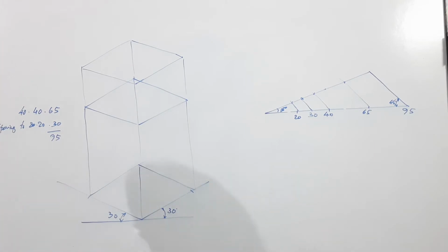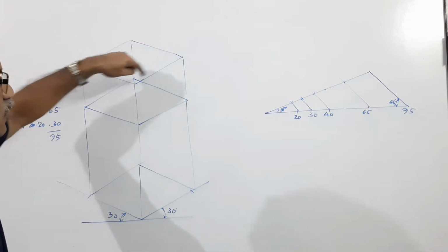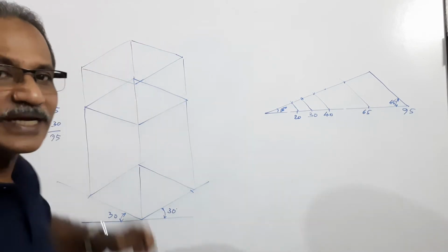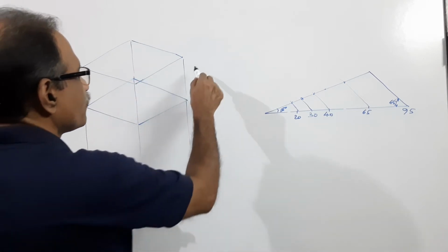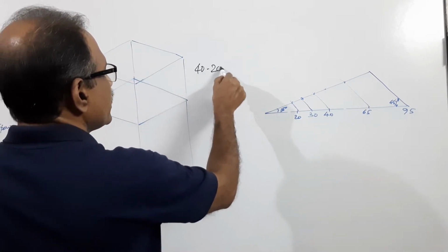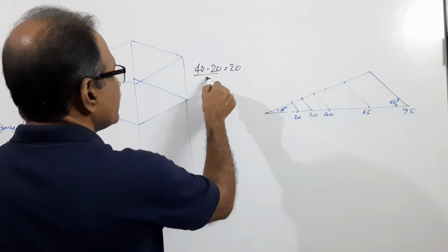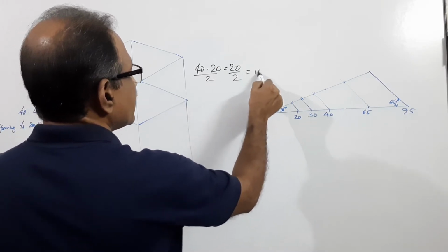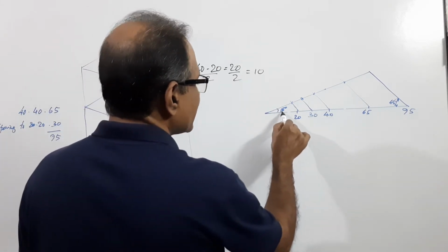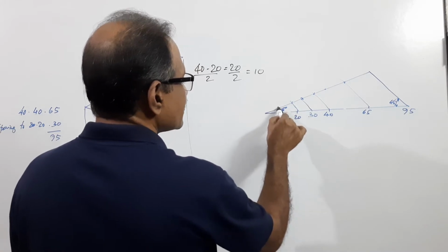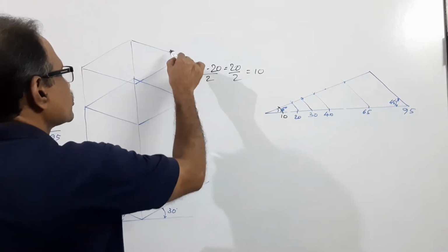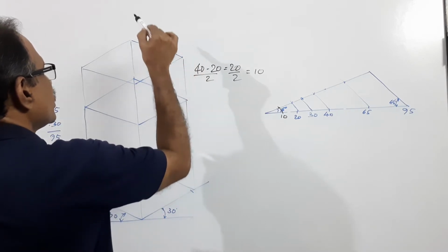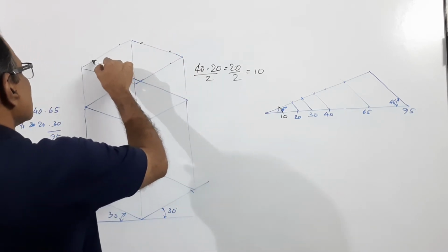Now, this is an ISO 40 rhombus. You actually want an ISO 20 rhombus there. What you have to do? You have to subtract 40 minus 20 equals 20. Divide by 2, 10. ISO 10. Mark ISO 10 here, get its ISO length, ISO 10. Subtract ISO 10 from all four corners.